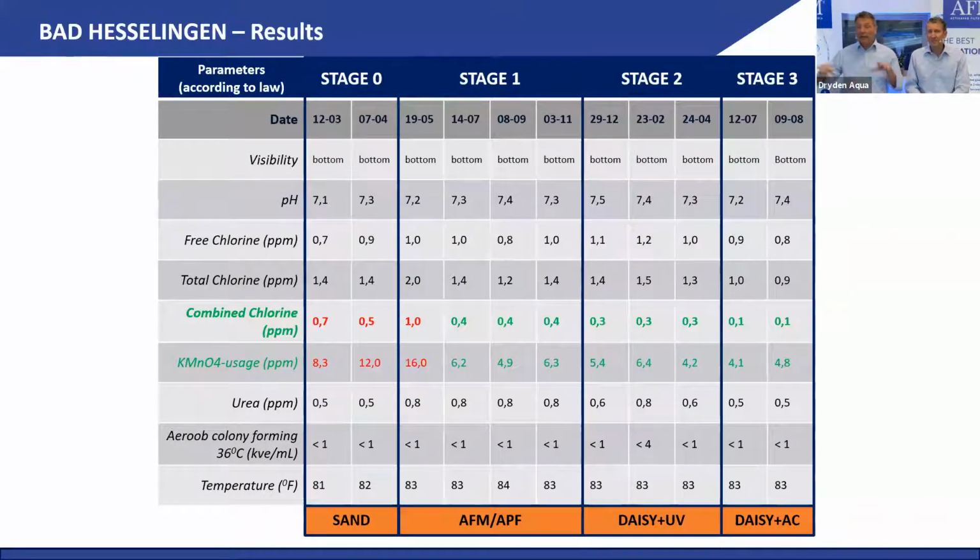Yeah, we are doing it. They have 2 pumps to backwash the filter, etc. So I can't believe it. I said I come tomorrow, but please first go there, make a video about the backwash process. So 2 hours later they called me and said, the bed is not moving. We instructed the operator to backwash with 2 pumps. This idiot, he's backwashing with 1 pump, and the other pump he even slowed down in the backwash process.